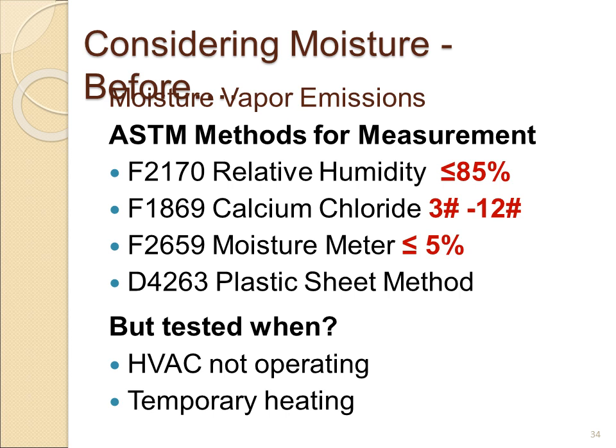A moisture meter helps you understand materials that are not going to really experience moisture vapor coming up from a slab. For example, if you're checking a plaster coat or a render coat, or a mortar bed. Typically mortar beds are over waterproof membranes, and you're concerned because the temperature's been cold and the material looks very dark, and you think there's a lot of moisture there. You can use a concrete moisture meter and check it. And if it's less than 5%, you're typically safe to install most products over that.